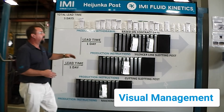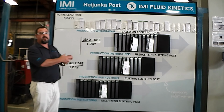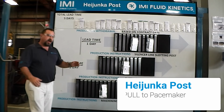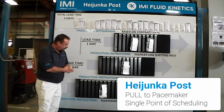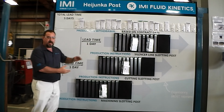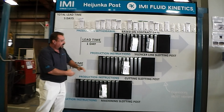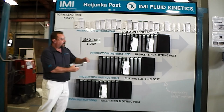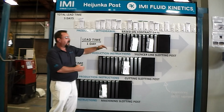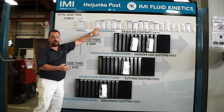What we've been able to create are parts withdraw, a 30-day window, a 30-day view of parts that we withdraw at our pacemaker, which is a pay by date. Our production instructions are then slotted in the Heijunka post. 2 poles per day in each of the different subs of the line. The production instructions for machining and then production instructions for cutting is offset by 1 day. And then 1 day offset also for the silencer line slotting, which equates to our 5-day manufacturing shop floor lead time in order to meet our parts withdrawal.